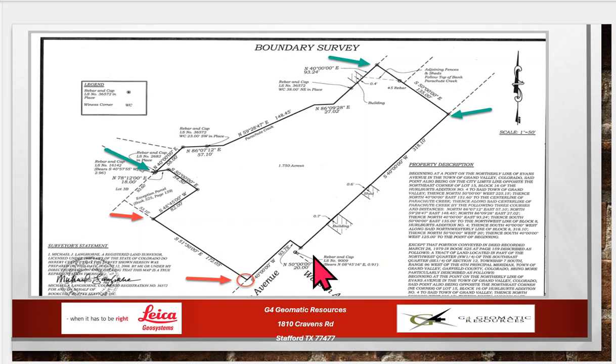Here's a schematic of a boundary survey just to illustrate. Let's imagine we found this point in good shape. We found the second boundary point over here. It looked kind of disturbed, but we want to hold this line here. It's not the best geometry, but we just want to use this to get on that local system. All these boundary points have been calculated by the office and uploaded, so we can use this to stake out and find these points. We probably find them within a few tenths accuracy, or 3 to 5 centimeters.